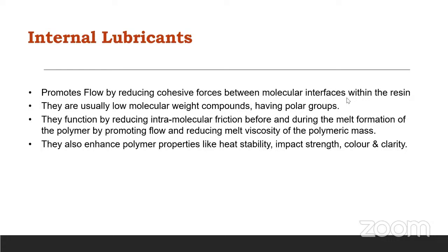So these internal lubricants are generally low molecular weight compounds which have polar groups in them, polar groups like COOH group, OH group, ester groups. They function by reducing the intramolecular friction before and also during the melt formation, and this promotes the flow properties by reducing the melt viscosity of your polymeric material.